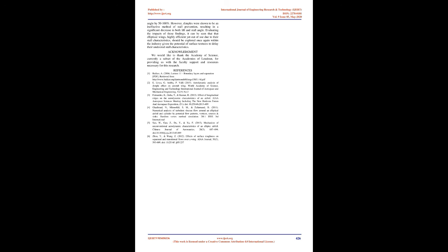Conclusions. Through this investigation, we were able to determine the effectiveness of 3 individual surface textures at stall prevention. Bumps and grooves were shown to be effective stall prevention mechanisms, increasing the peak stall angle by 50 to 100%.